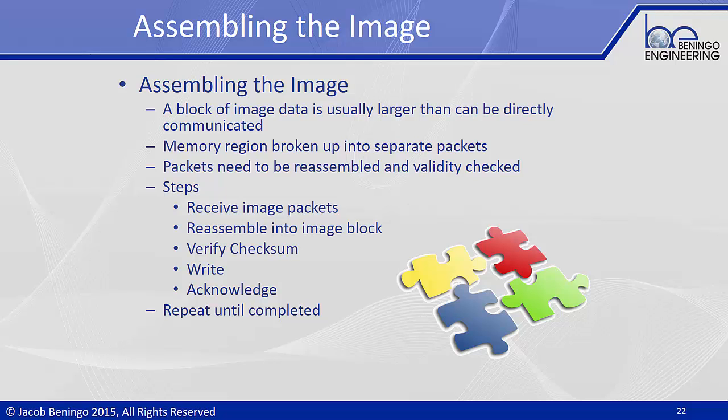So as you can imagine, this tends to be just a simple process that is repetitive. Once you get one packet down and you're able to write it, it becomes a repetitive process of just acknowledging and verifying that the data is getting there. Until you get to the very end and maybe you write an application checksum in the flash and then you perform the system restart.